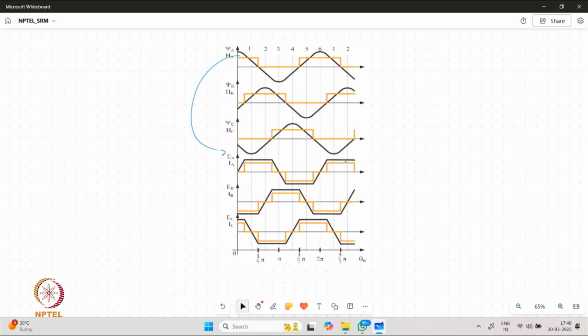So which is why we say that this is a non-sinusoidal structure, and to identify whether we are dealing with a permanent magnet synchronous machine or a brushless DC machine, this is one of the ways to identify that. If we operate the motor mechanically without any electrical connection given to it, we are going to find the back EMF going in a trapezoidal fashion or nearly in that manner.